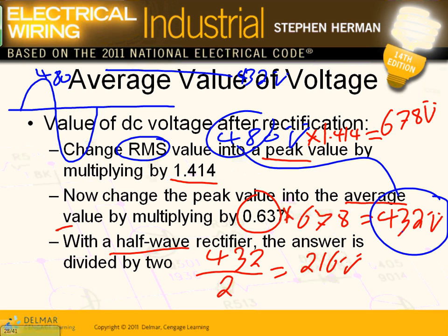So I know my voltage is 432 now, and I want to tie 10 kW on it. You take the 10 kW and divide it by 432, and that will get you the current. Does that make sense, guys? The current is a function of the load that's coming.